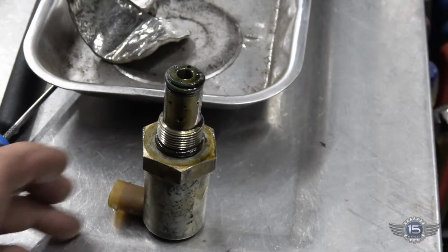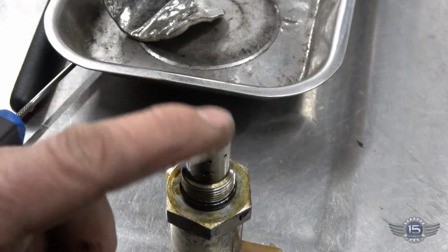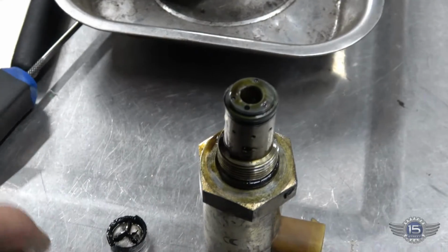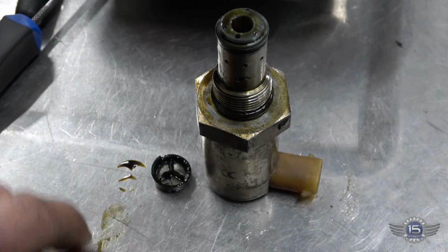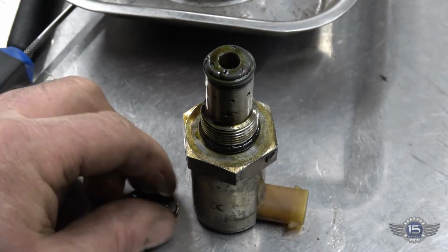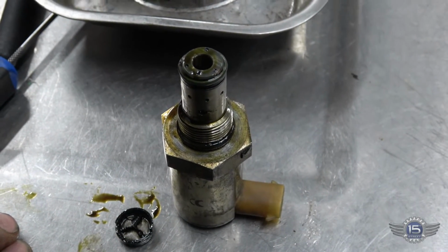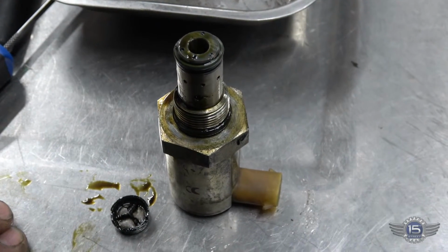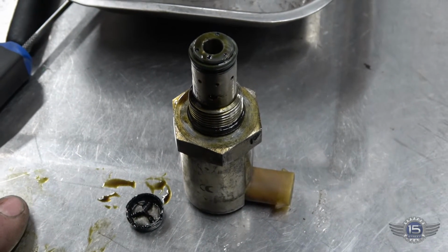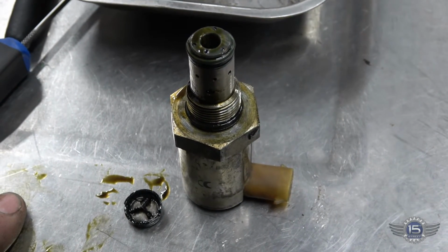So one thing I noticed when I pulled this IPR out of there is there's usually a screen cap on there, and what I found was this cap was still stuck in the pump housing. That's supposed to snap onto there, and it was still stuck in there, and the screen's blown out of it. So that tells me there's probably been some debris from that pump gone through this thing. So more than likely we're looking at a pump. I got no leaks. I've got a questionable IPR, but with the IPR removed I still don't have any pressure, which tells me that pump is probably failed. So looks like this thing's getting a pump.